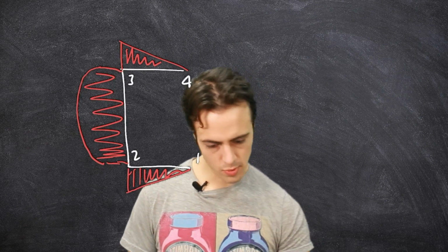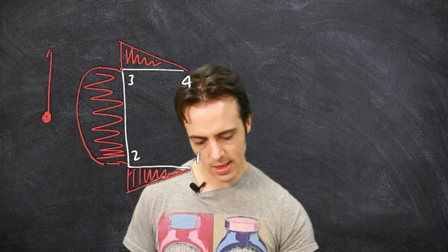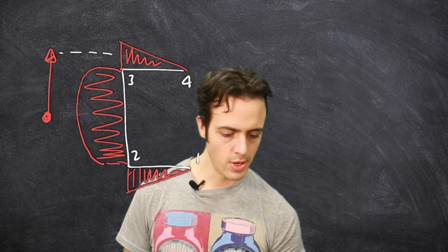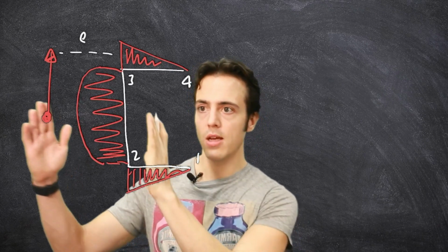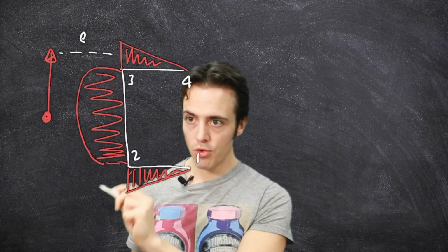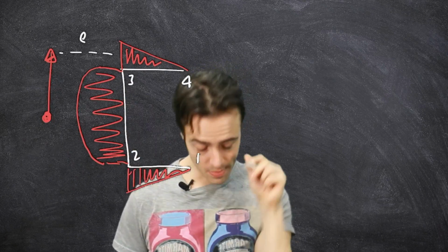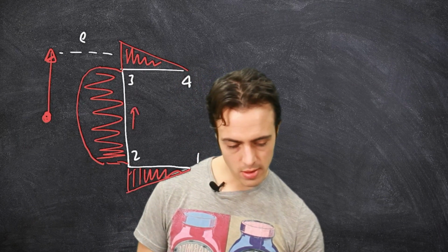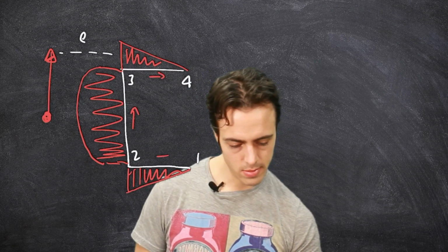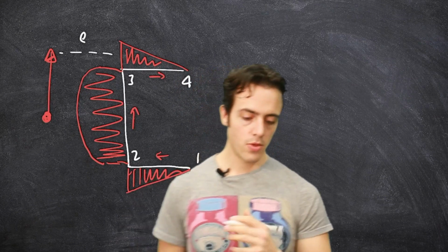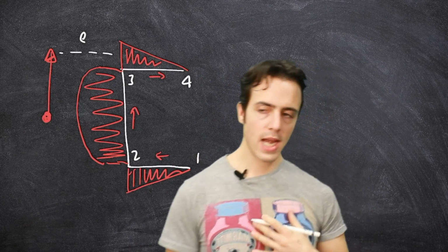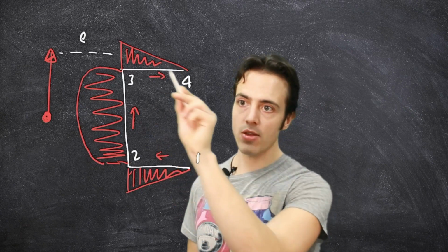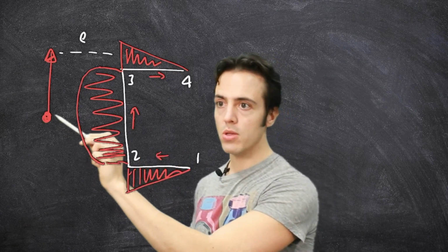Because we loaded vertically, let's say that we loaded at distance E away from the centroid of this vertical member. So that means that my shear flows are going in this direction. We now need to find a condition for which the moments due to these three shear flows equal the moments due to this.